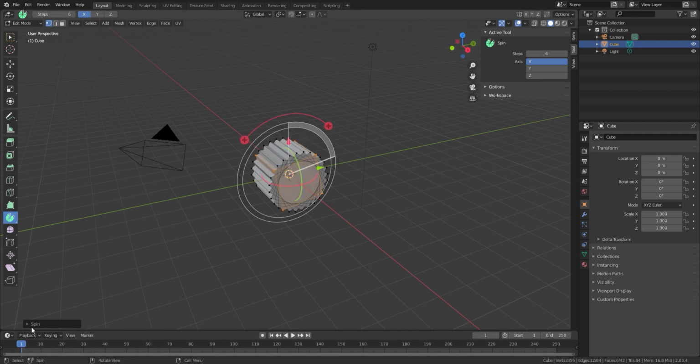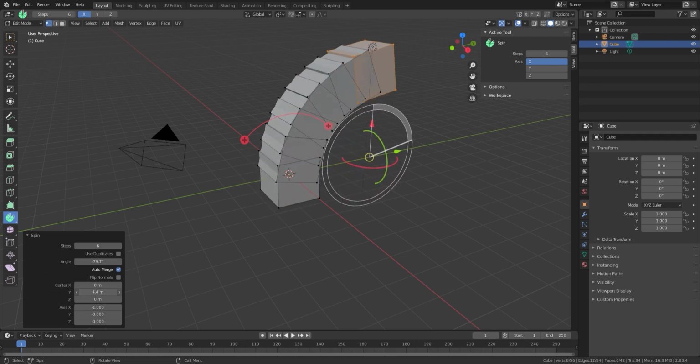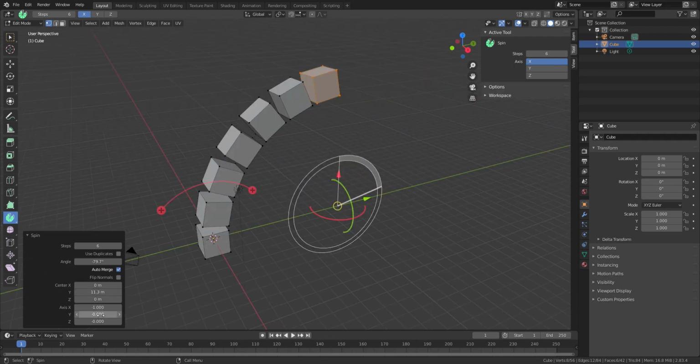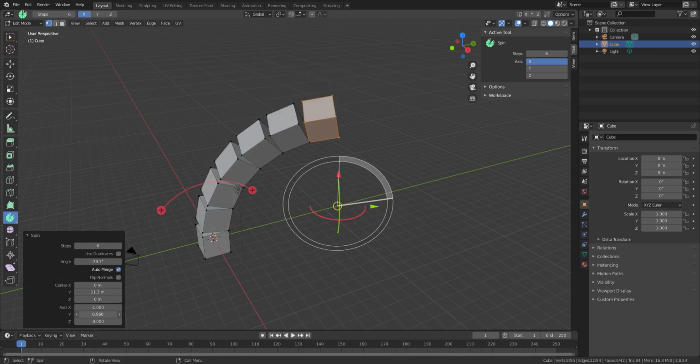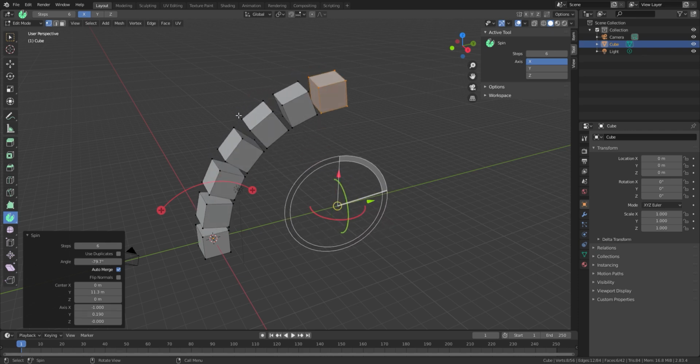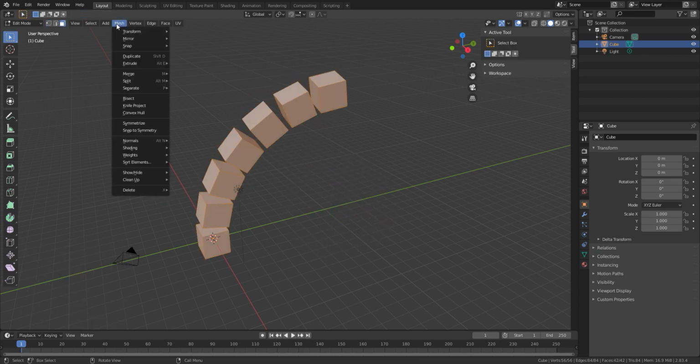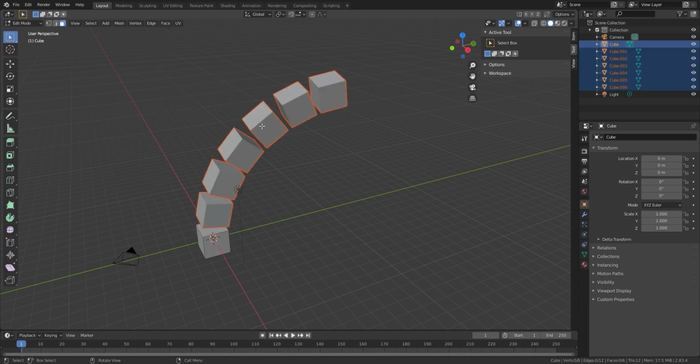In the left corner below, let's open that window. In the upper section, we will move the axis. Below that, we spin it until we get the desired results. For the separation, all the polygons are active. Now we choose Mesh, Separate by Loose Parts.